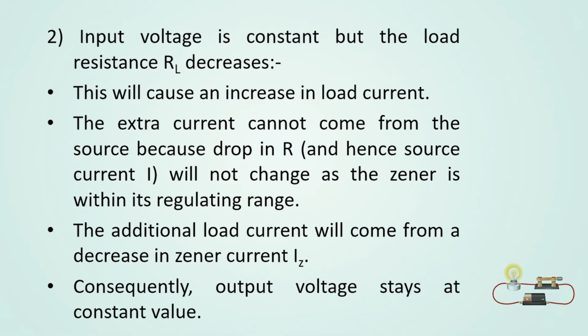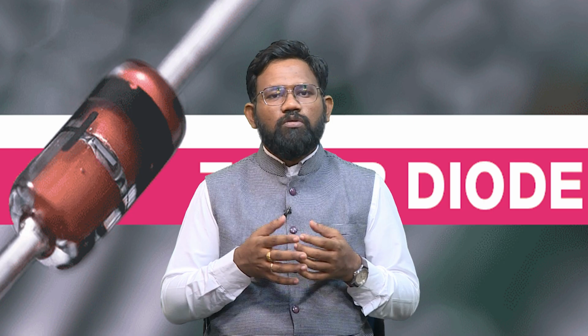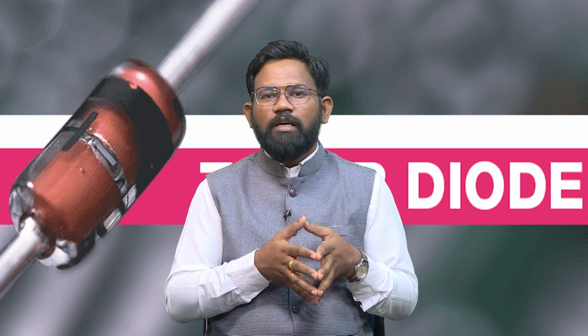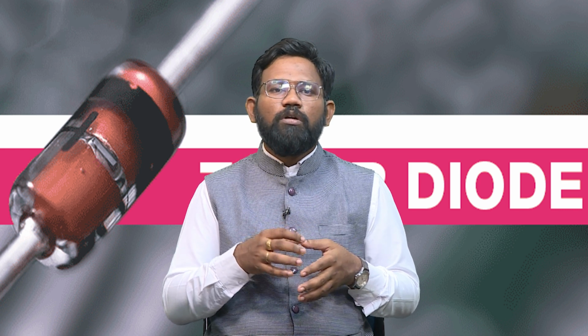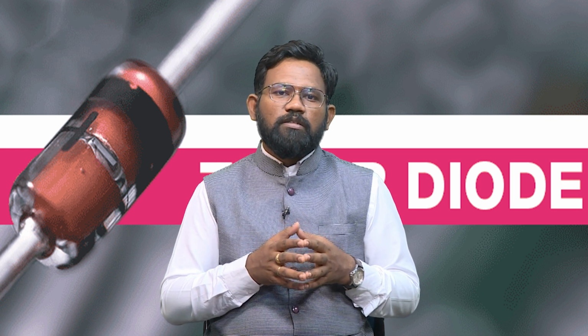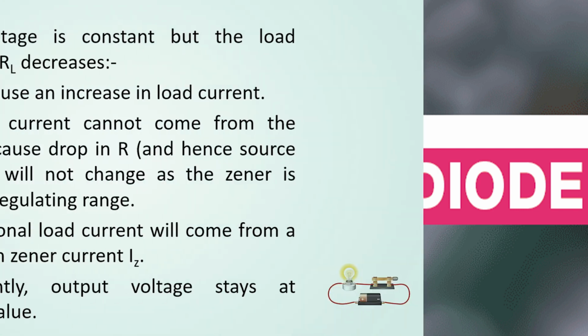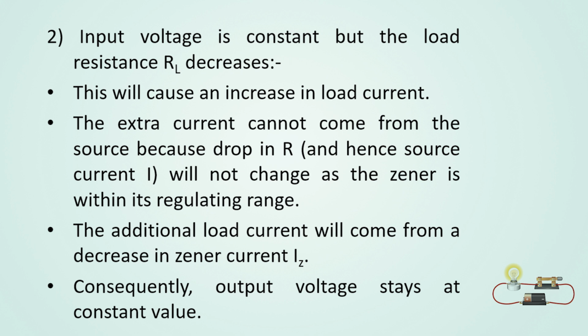Now, let us see the second condition, when the input voltage is constant, but the load resistance RL decreases. So, what happens when the input voltage Ei remains constant and the load resistance RL decreases? This will cause an increase in load current. The extra current cannot come from the source because the drop in R, and hence the source current I, will not change as the Zener is within its regulating range.